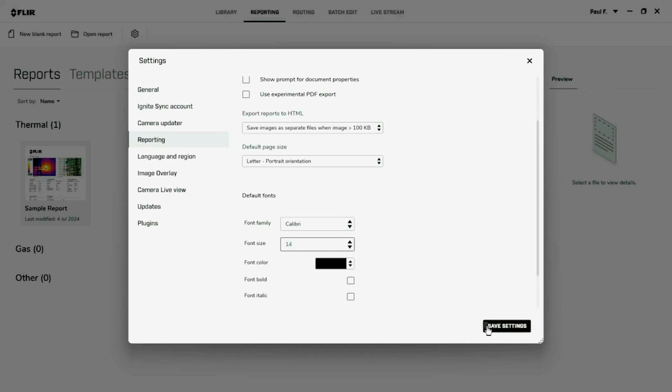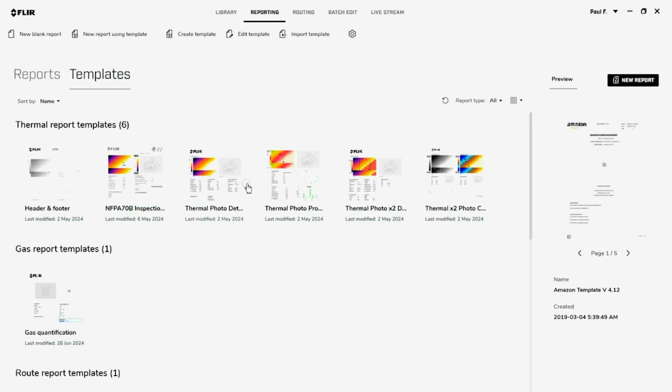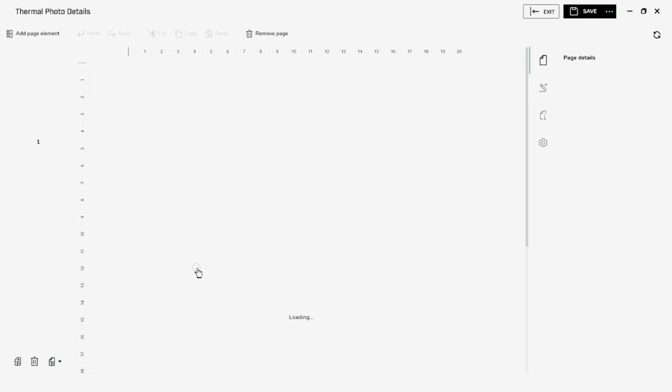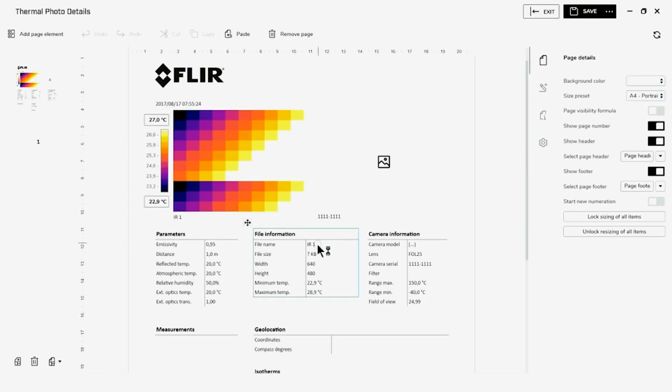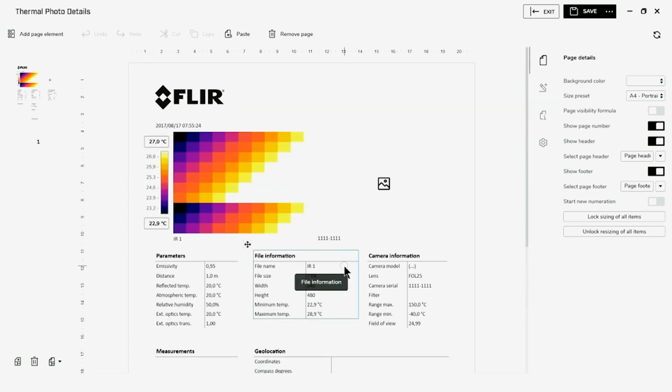Before designing your own template, it is suggested that you review some of the installed templates that came with Thermal Studio. One of them may have a majority of the options that you would like in a report, and it would be a simple matter of editing that particular template. Choose a template, right-click on it, edit it, and review whether the contents of this particular analysis page are of your liking.